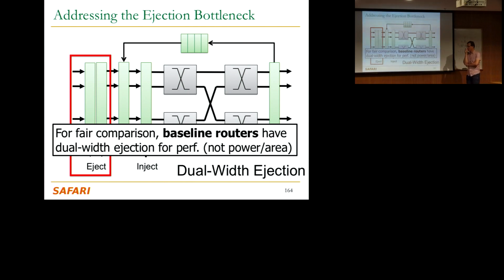Router, because I think it resembles, it's not identical to, the various techniques of the power of choice among two. Yeah, now it gives you 2 candidate slots. The immediate and the next. And because the other traffic coming in is unrelated, exactly, it's like flipping a coin twice. Your probability of failure to get your way is P. The probability of failing twice is P squared. So basically a single slot buffer as opposed to 4 flits. Single slot, and either you go or you get deflected. You can't even spend more than one there.